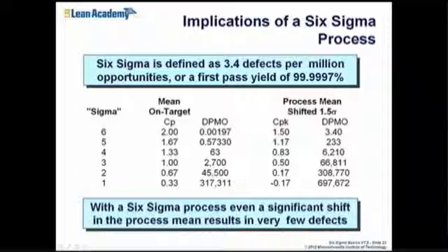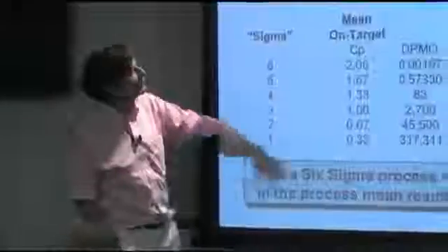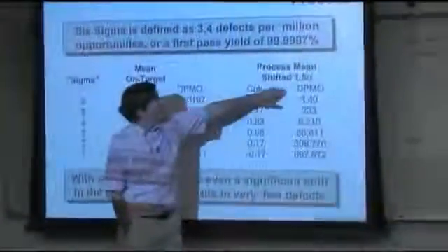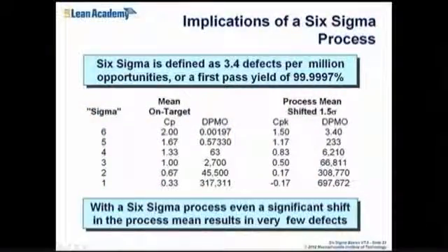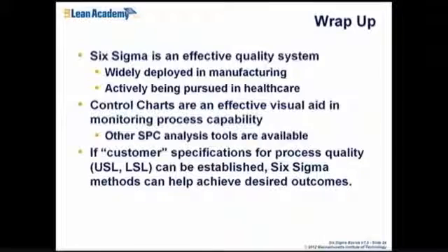Remember we said I'd tell you where the definition of 6 sigma comes from. Interestingly, it comes from a process with a mean shift of 1.5, which would give you 3 defects per million opportunities. So if you have a very good process, but you still don't control your mean to more than 1.5 sigma, you still have a very low defects per million. That's where that idea comes from. Those are some of the concepts that we use to get processes under control and keep them there.